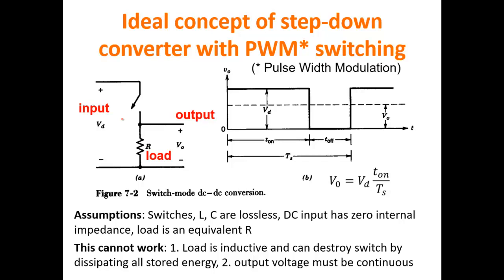For example, it has a small inductor in series. The problem is that the inductor is inertial with respect to current. So if you try to rapidly change the current in an inductor from a finite value to 0, the inductor resists this behavior and modifies the voltage at its ends in order to counteract this behavior. And this is exactly what happens here.